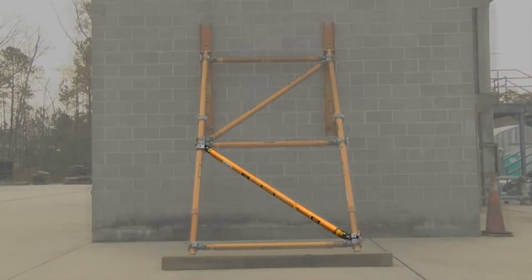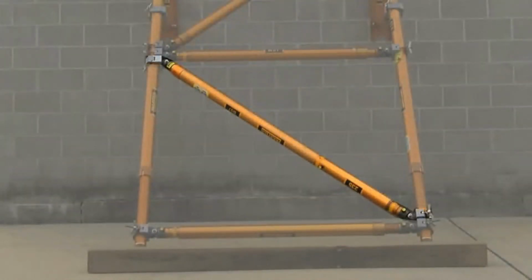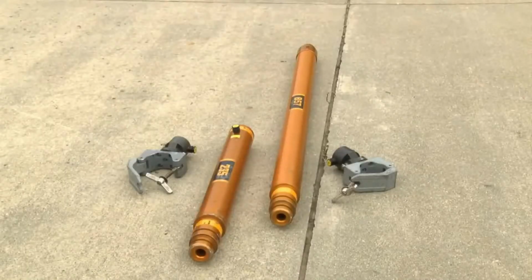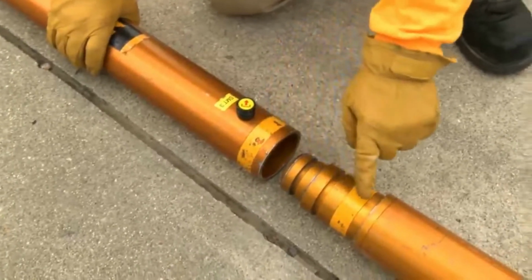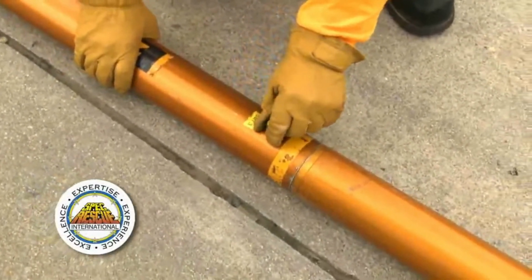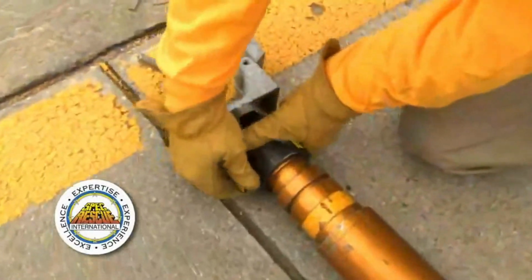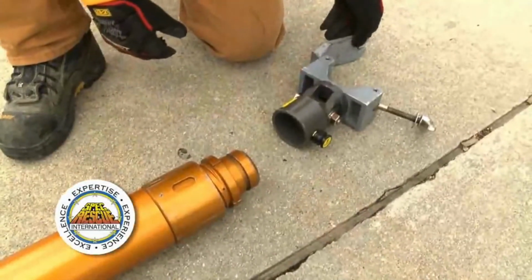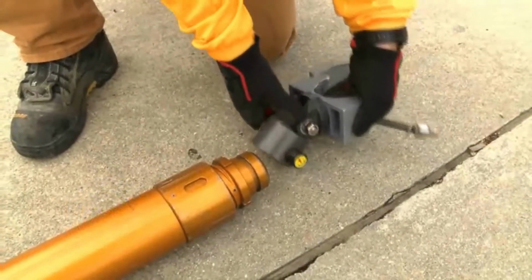Now assemble the diagonal brace, which is longer than the lateral brace. The lateral brace was a B57 by itself. The diagonal brace is going to be a B57 with 235 extension. Notice the matched yellow tape to yellow tape to make sure the extension went on the correct end of the brace. Attach the clamp and clevis on the non-movable end. Move up and attach the clamp and clevis to the movable end.